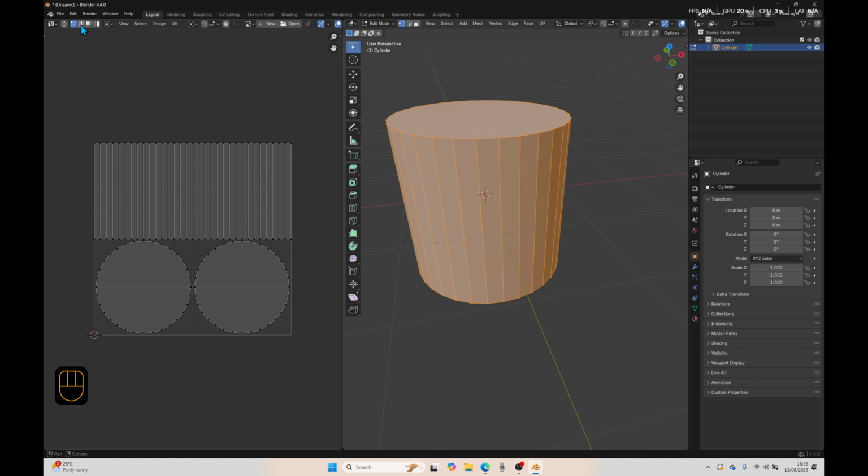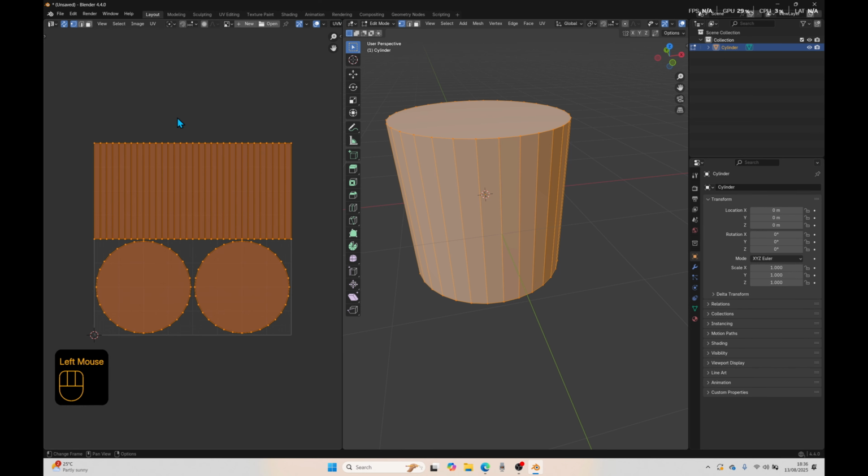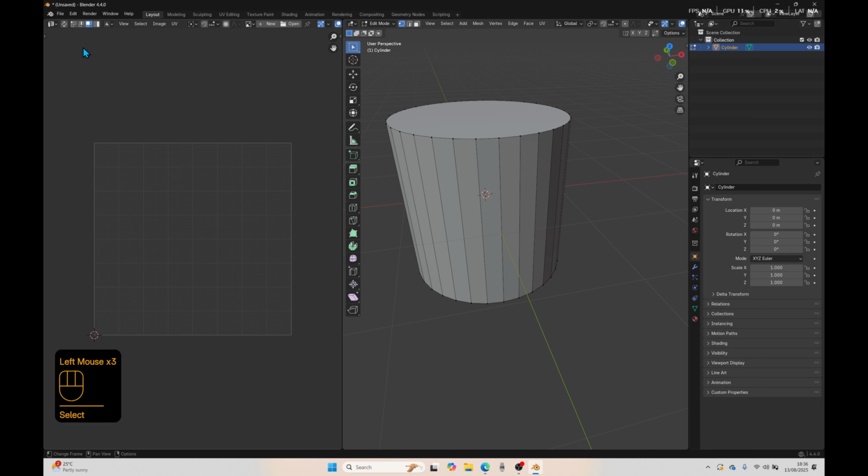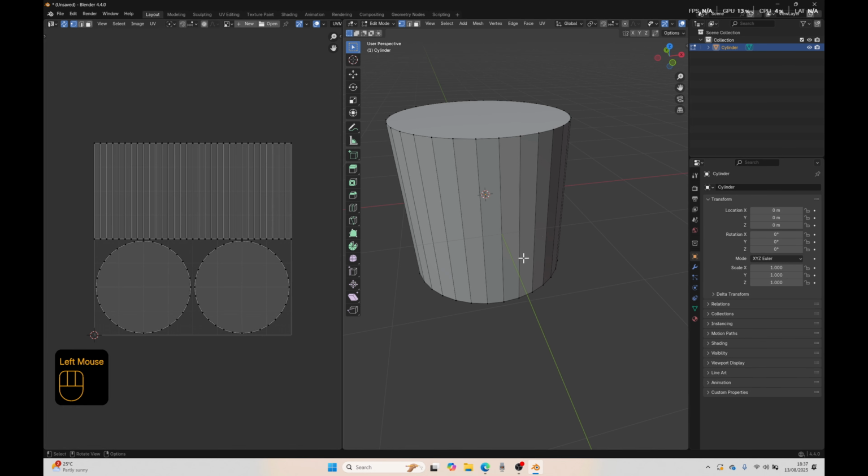We've got vertices select, edge select, face select. I just select face select and then click these arrows, which is UV sync selection. Okay. And that just means by clicking those arrows, if I click them again, because nothing is selected in my 3D viewport, I can't see anything in my UV editor. But if I click sync selection, you can now see, even though I haven't got anything selected, we can still see the UV map. And that's normally ideal. There are exceptions, and if we ever need them, we'll cover that in future lessons.